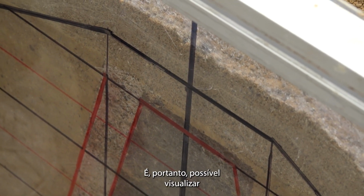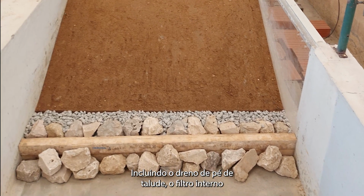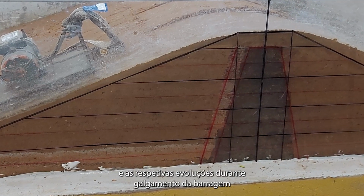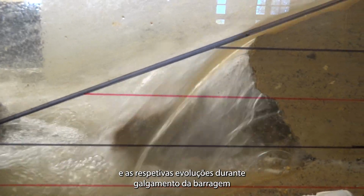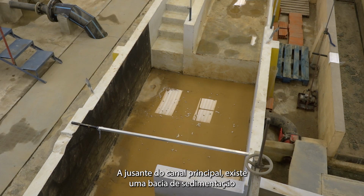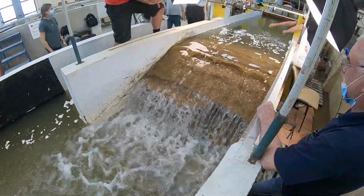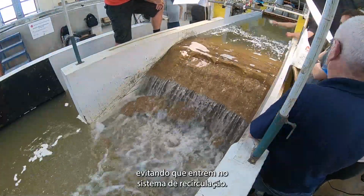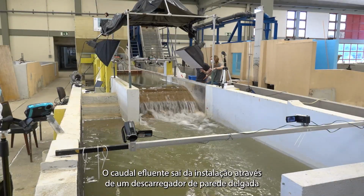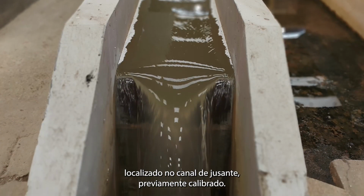It is thus possible to see all the layers composing the dam, including the bank toe drain, the internal filter, the vertical drain and the core, and its evolution while the dam is overtopped. Downstream the main channel, there is a settling basin where the sediment removed from the dam body are deposited and prevented from going into the recirculation circuit. In the downstream channel, perpendicular to the latter, the effluent flow exits through a calibrated V-notch weir.